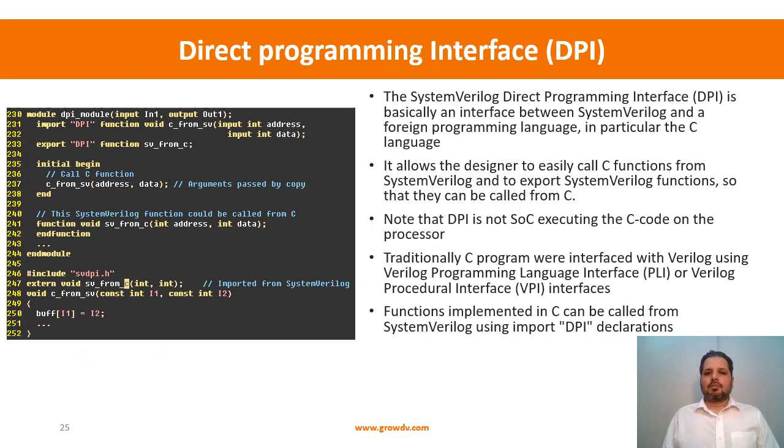There are some cases where some parts of the testbench are implemented in C. We are not talking about an SoC processor executing C code. This is as a simulation engine: I am simulating both the SystemVerilog as well as the C code. It's not running on some processor. Even a design that doesn't contain a processor may want to implement something in C, so I can use that C code over here.